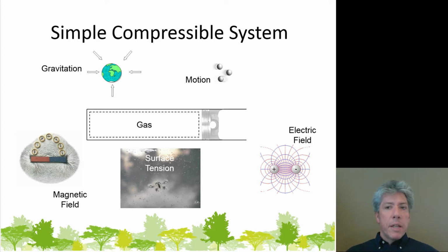If you're going fairly fast, your engine's moving fairly fast, and if you've ever stopped to think about how fast a piston moves up and down in the cylinder that it rides in, it's pretty doggone fast. It's actually pretty impressive what kind of accelerations that piston has to experience and not fall apart. Anyway, now let's consider the gas above the piston. You're still going around your curve real fast, right? And there are air molecules in the gas. Are those air molecules really going to slosh to one side like the gasoline does? Or is that acceleration really significant by comparison to the acceleration being caused by the piston? Probably not. The acceleration of the gases being caused by the piston's motion is going to be a heck of a lot higher than their acceleration due to the bulk motion of the vehicle.